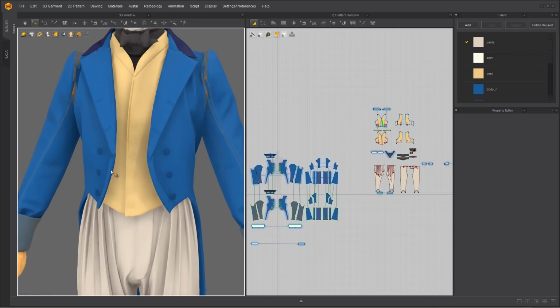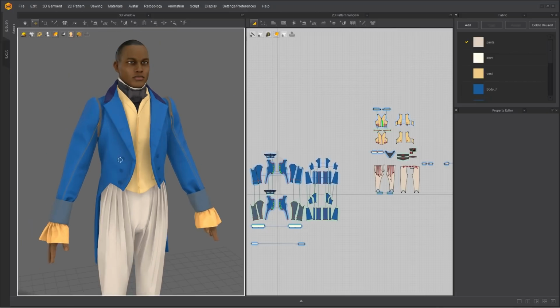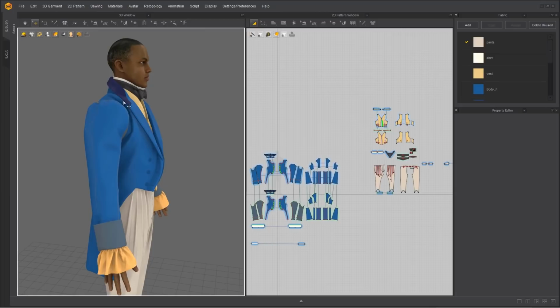Michelle also used a trick here to create a thickness to the material without increasing the simulation thickness, which is to create a lining. You can do this quite easily by right-clicking your pattern pieces and choosing the layer clone over or under options. This allows you to create a thickness of the material without actually having to increase the thickness itself for export. So let's go ahead and we will move on to the shoulder pieces here and use partial solidify.